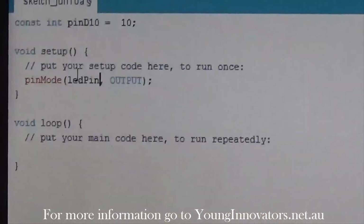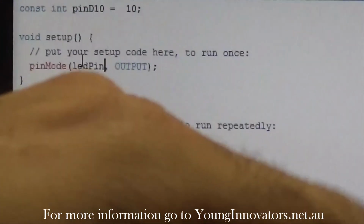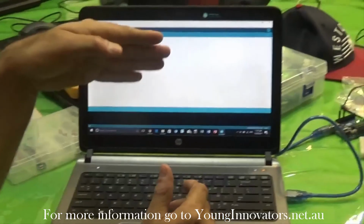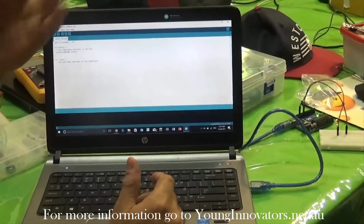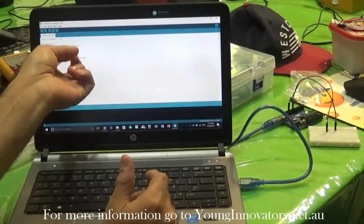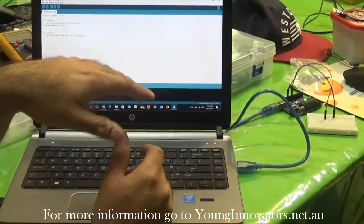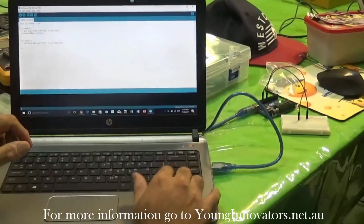Control V. Okay, yeah. Okay, so pinMode. These pins, 0 to 12, can be input pins or output pins, right? Input means they are listening, they are sensing. So when we create the sensors, those pins will become input pins and they will sense what's happening. If it's an input pin listening to temperature, the pin will sense what the temperature is, right? But right now we're using it as an output pin. So output is always electricity, right? It will output 5 volts, right? It has a symbol next to it as well.